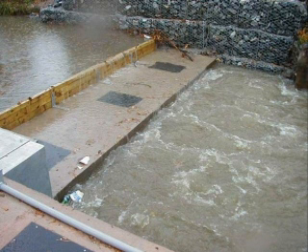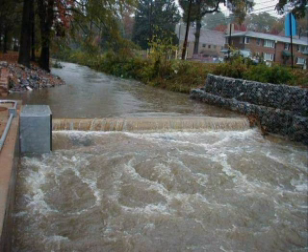The filter itself, in a dry weather state, is uncompressed. It's similar to the compressed media filter that was used in the CSO facilities in Columbus, but in this case there's no mechanical devices pushing a plate up and down. What we found in all the testing we did was that we need that surface of the compressed media filter uncompressed. That way the big particles get removed on the top surface.